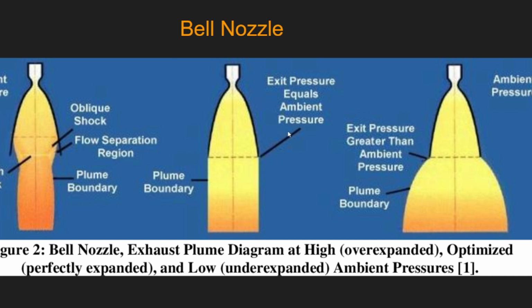Now we have the rocket nozzle as it is at its design altitude. At this design altitude, the rocket plume's pressure is supposed to be equal to the outside ambient pressure. This way, both of them will be pushing at each other with an equal force, therefore all the velocity is perfectly straight down. Now as you go higher and higher in altitude, the ambient pressure is far less, and this results in the high pressure inside the plume pushing outwards more than the outside can push inwards, hence it is expanded and some of the velocity is directed outwards. This way, if we take the cosine of this angle of the velocity, you can clearly see where the name cosine loss comes from.